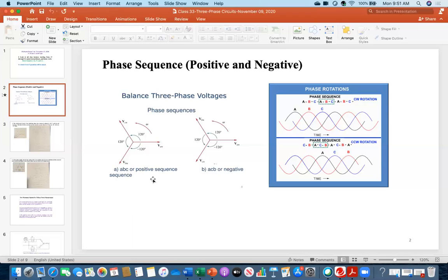So once you notice, you immediately stop the system, meaning your phase sequence is not matching. That is the problem. You don't need to go further beyond this. You just remember that there are two types of phase sequence in the three-phase system. One is called ABC, the other is called ACB.